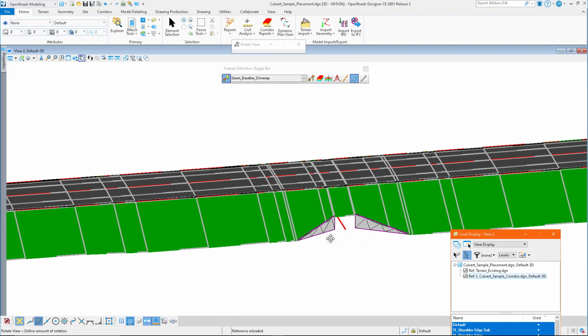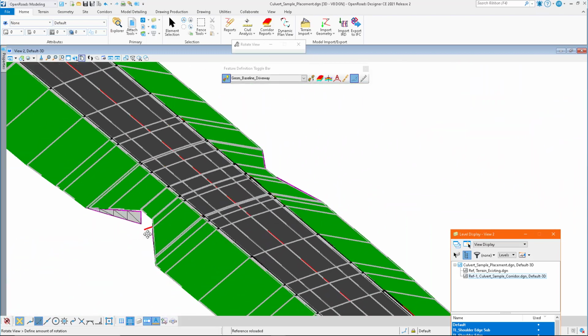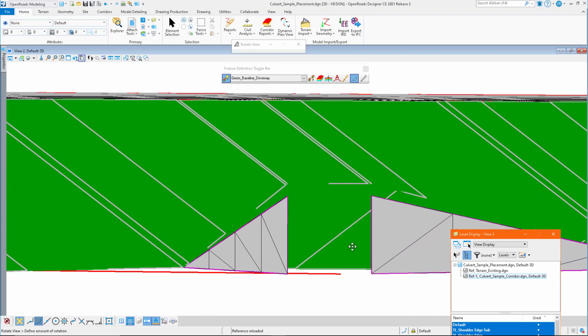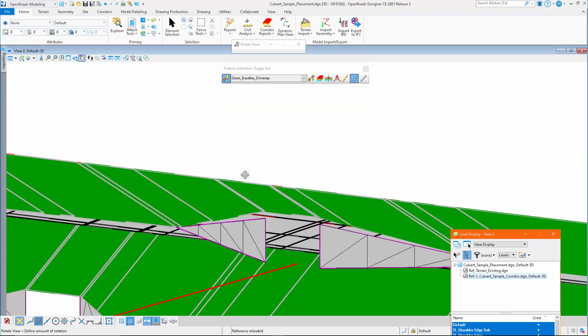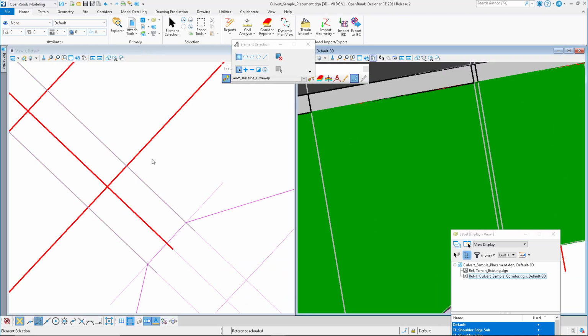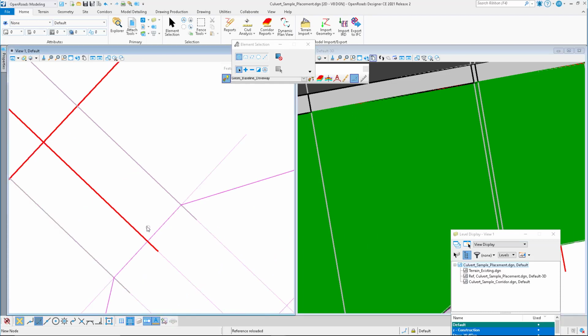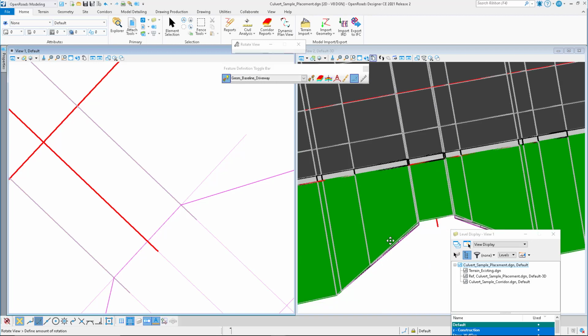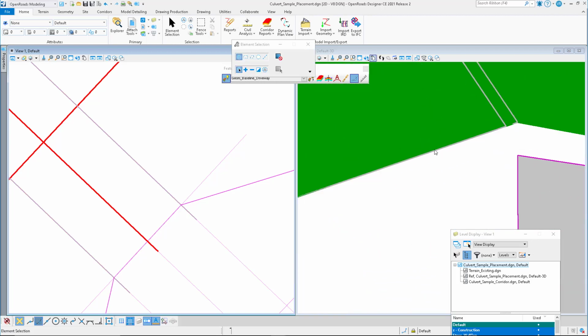you see that everything's nice. And here, well, everything's not nice because the location is correct, but you see that the head wall is after the markers, so the wall is not high enough. And because the culvert is not long enough, that means that I have to make it a little longer.